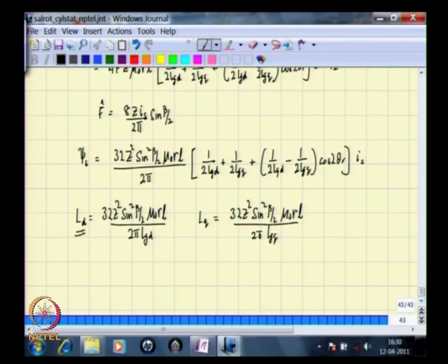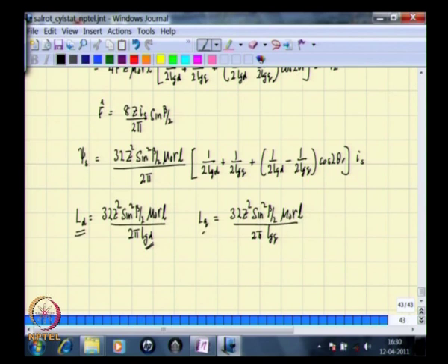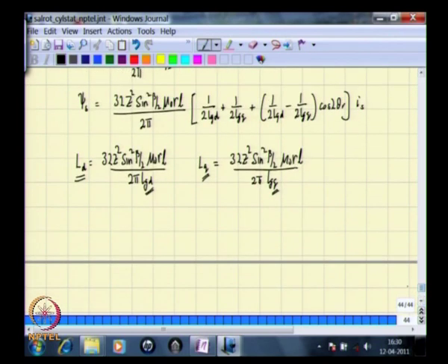This inductance LD is representative of the assumed cylindrical rotor structure with an air gap of LGD, which is a smaller air gap, and another inductance LQ which is representative of a cylindrical rotor structure which has an air gap of LGQ, which is a larger air gap, and the larger air gap is the one that is present along the quadrature axis 90 degrees to that of the pole face. So we will call this the quadrature axis inductance,